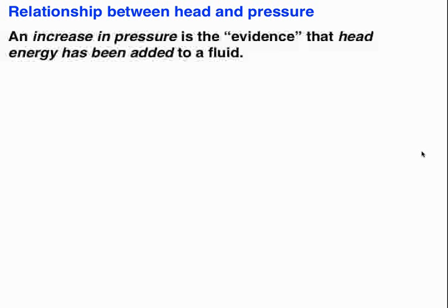Here's another misconception, that head and pressure essentially mean the same thing. Well, they don't. It's like heat and temperature. Heat and temperature are related, but they're not the same thing. And the best way to think about this is as follows. Whenever the pressure of a fluid increases, that's the evidence that head energy has been added to it. Okay? In other words, an increase in pressure is the evidence that head energy has been added to a fluid.